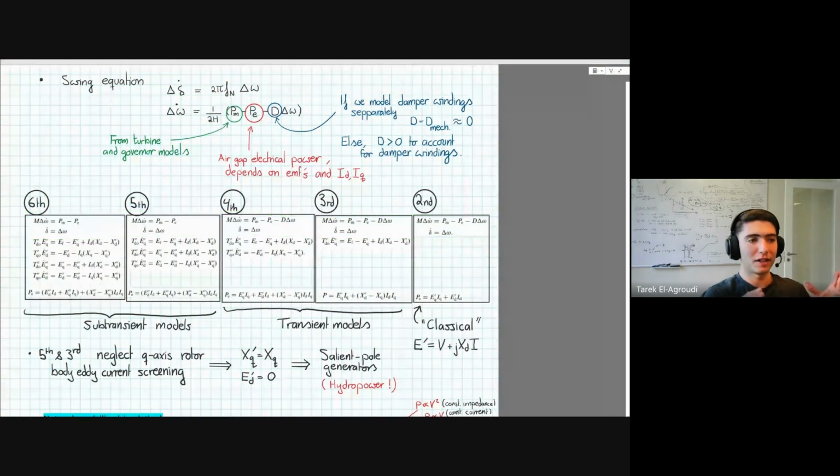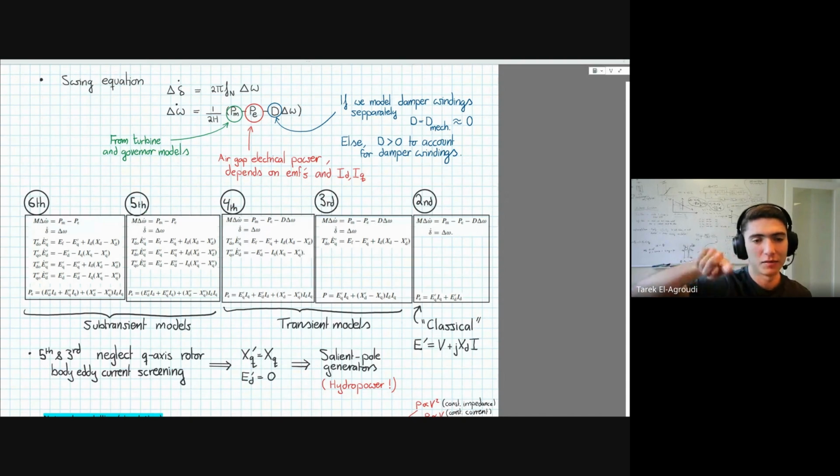Very briefly put, how I understand it, the synchronous generator is a rotor, which is basically just a coil which rotates inside an armature or stator. And this rotor is driven by some turbine, so typically hydropower or steam or something like that. And this generates a mechanical power which accelerates the rotor. The stator or armature around the rotor has 3 coils. And in these coils, the rotating rotor generates some voltages due to electromagnetic effects, which we'll get to.